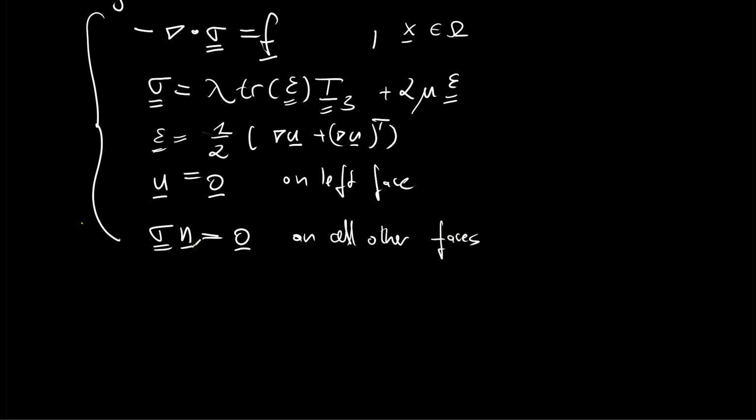And the reason this is a Neumann boundary condition is that if we just use the sigma matrix, we have exactly one derivative in it. And that's basically also the property of the Neumann boundary condition, that we are not prescribing the actual primary unknown on the boundary, but we are prescribing its first derivative. And with the unit normal vector, we are also letting it point into the right direction here.